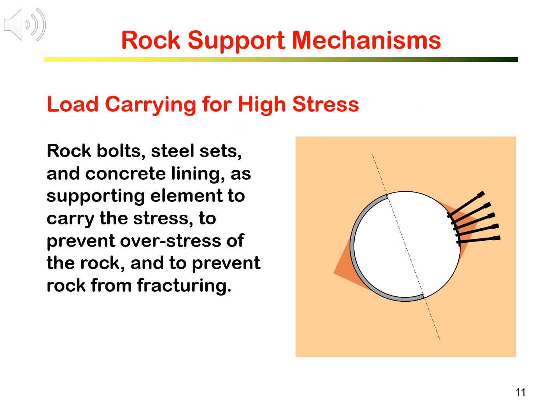For underground excavation suffering from very high stress, for example, at great depths or in tectonic regions, support is applied to take the high stress so the rock around the opening is not overloaded to fracture and to break. Rock bolts, steel sets, and concrete lining can be used as supporting elements to carry the stress. This is illustrated by the figure here. The support must be designed to be sufficiently strong to bear the high stress.